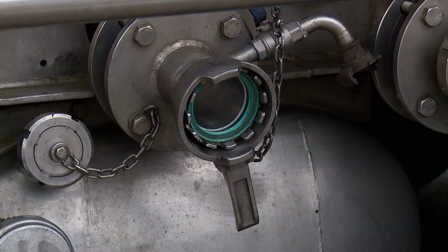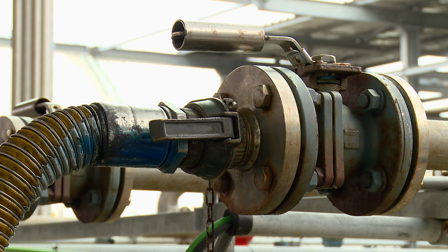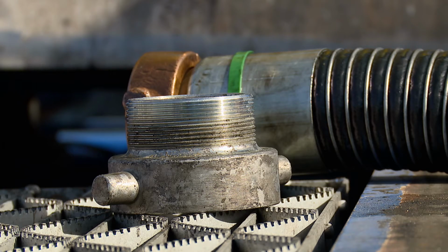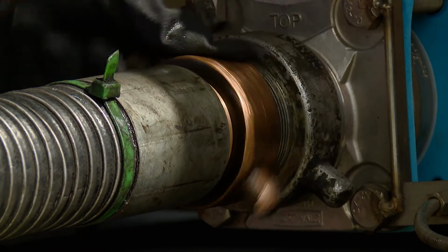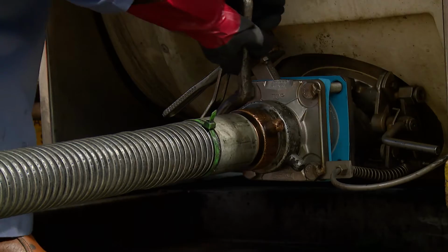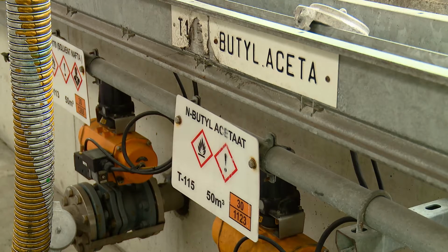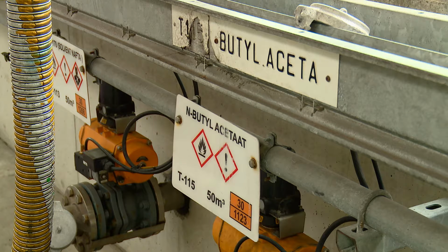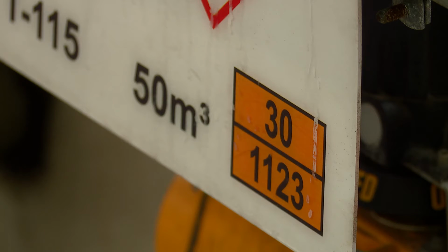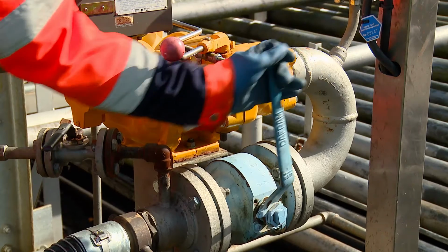Connection fittings may differ between tanks and sites, which will have been established during pre-delivery inspection. This will be covered later in the film. The hose is connected to the tank, with the valve remaining closed until final checks are complete. For discharging bulk solvent, the connection point on the receiving tank should be marked with the product name or UN number and is opened by the site operator.